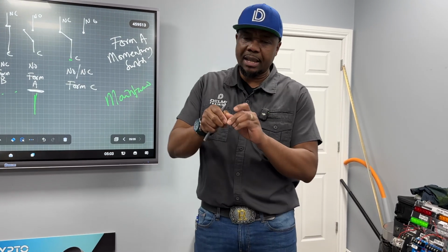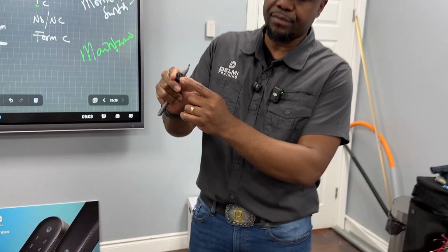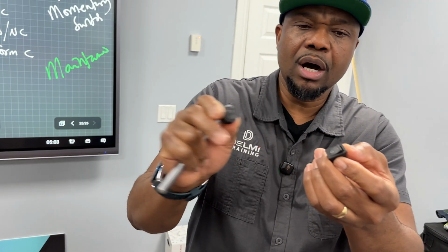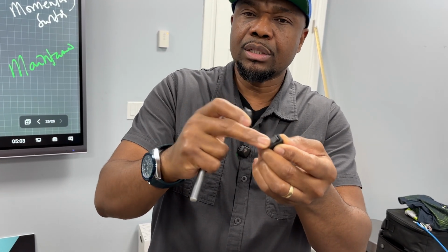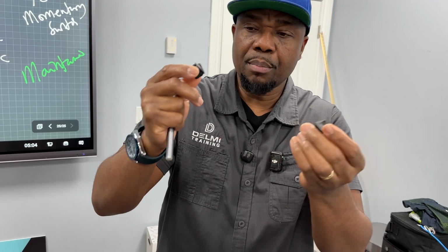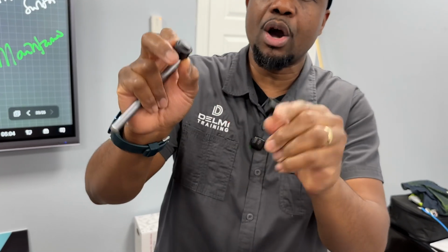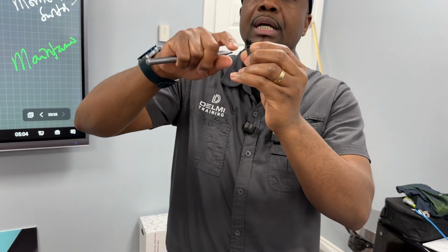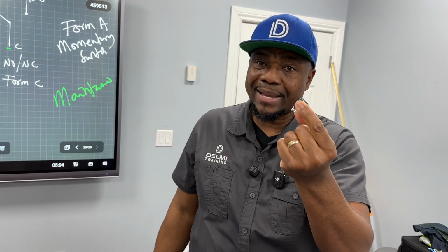In the same time, when we look at these ones, this has an on-off. It's your typical switch. So these are also on-off switches. They make or break. So the default state from the factory is in the off state, meaning that this is an open switch, but when you toggle it, it's going to close and remain in the maintained state.